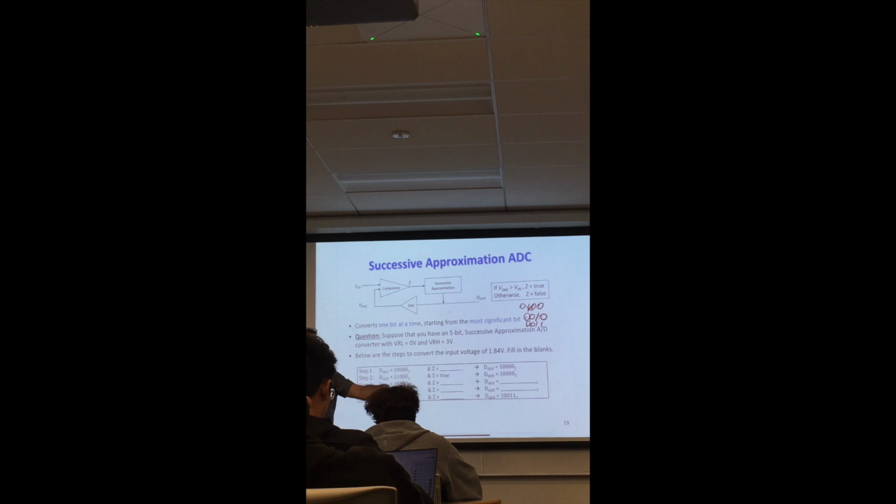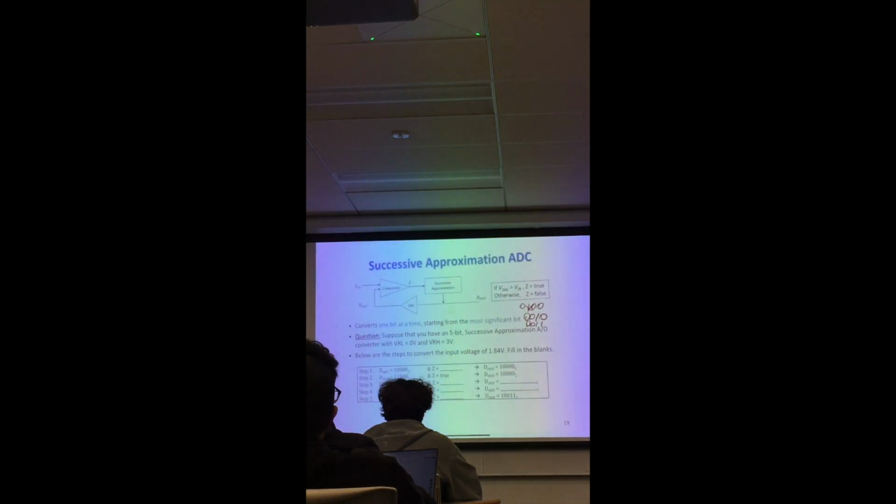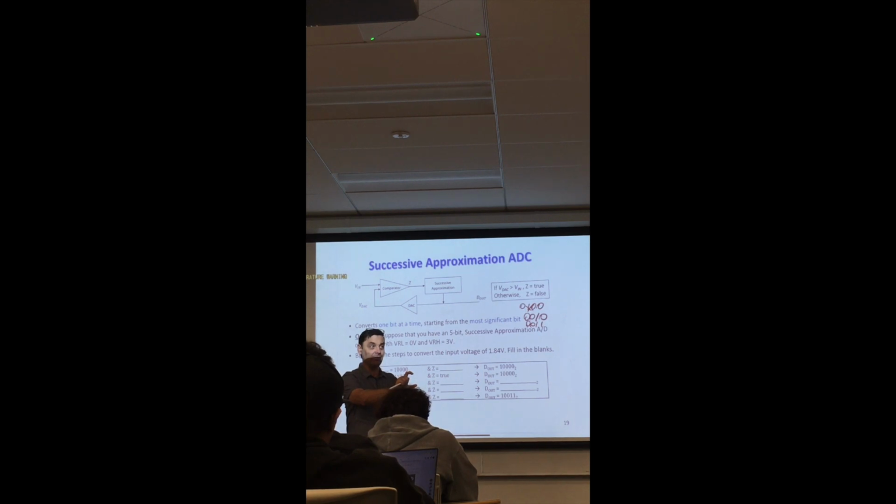Of course, you can say, I will use 16-bit precision in order to increase the resolution. But the problem is that 16-bit requires more time for processing. What if your process is too fast and this 16-bit processing is too long? You may actually lose some information. So what do you do? Change the range and lower the precision of the analog to digital converter, and your resolution will be extremely high at the cost of lower processing speed.